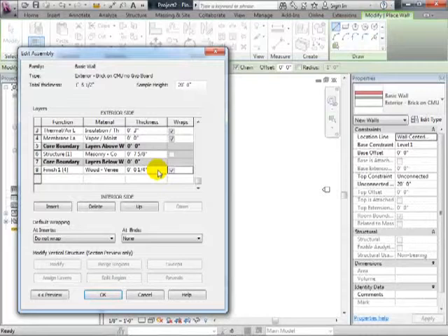How do you show ties, for example? Ties are a little bit hard in terms of doing that. The big question is going to be whether we want to do them in 3D everywhere or just in 2D, like in this section. In 3D works. We'd have to create a tie family, and go ahead and insert it in the places where you do want to see it. You can't insert it within this definition. No, I wish you could. Some things that you can do. Let me just give you variations on this theme.